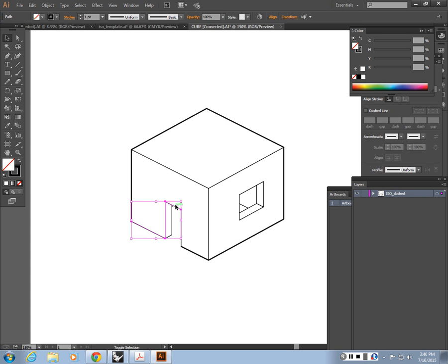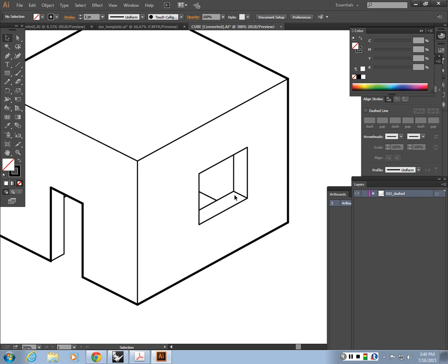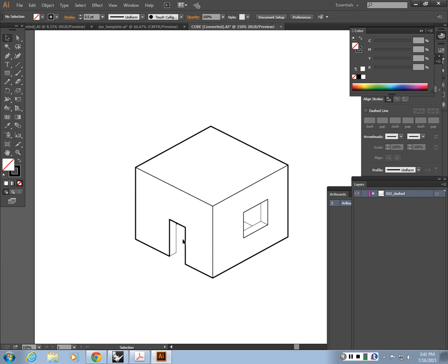And since the wall is connected to them, I'm going to keep the same line weight. So I'm going to keep extending the line weight. So this is all 2. This is 1. I'm going to make this one the same line weight. Well, this guy is inner detail, so let's make them thinner. So these guys could be 0.5, which will add more depth. Same as here, right? So these could be 0.5. Okay? How does that read?